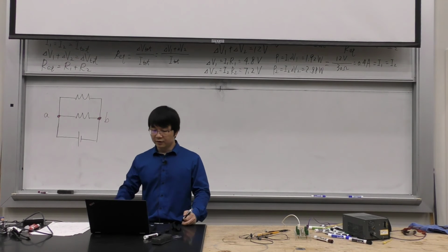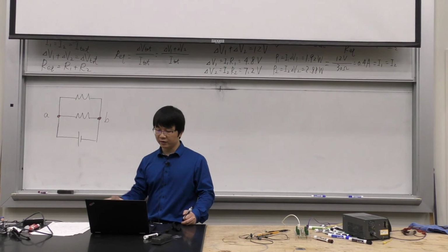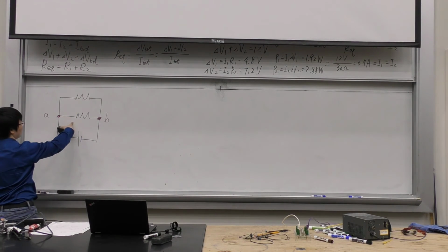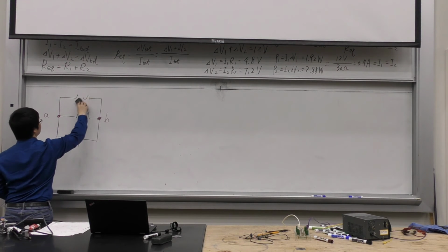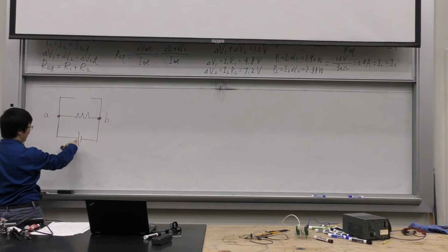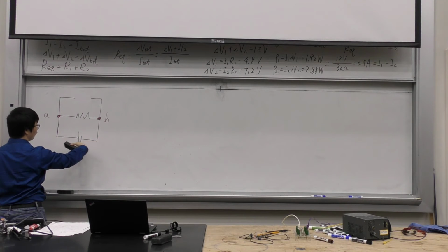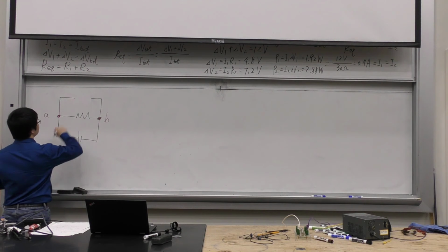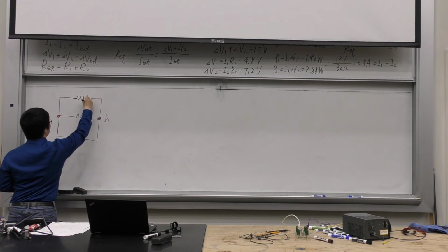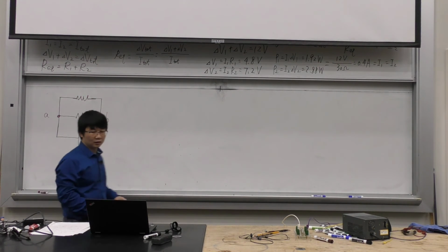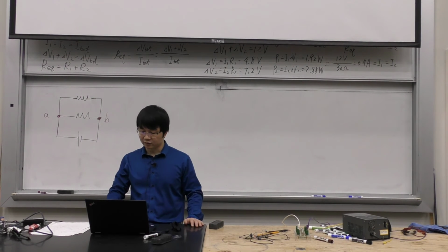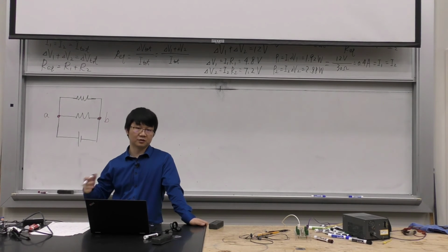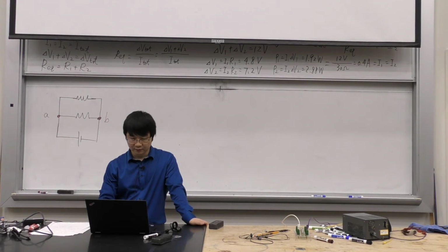So in this case, each resistor is totally independent of the other one, right? You see that this guy is totally independent of this guy. If this guy breaks, this guy opens. There's still a path for the second guy to form a closed circuit. So the second guy is not going to be affected at all. So that's the advantage of a parallel circuit: when they are totally independent of each other, a failure in any one path is not going to interrupt the other paths.